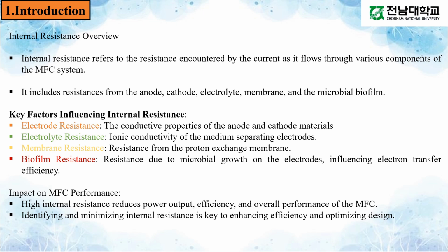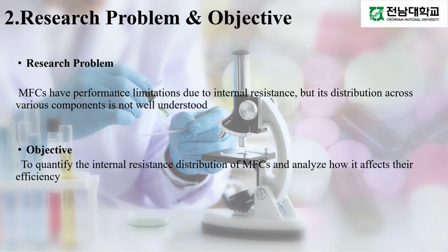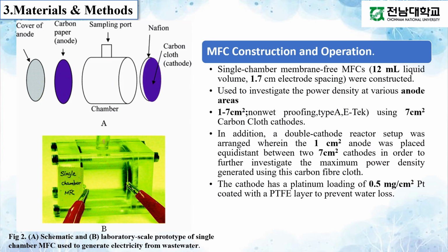The research problem of this article is that microbial fuel cells have performance limitations due to internal resistance, but its distribution across various components is not well understood. The objective of this article is to quantify the internal resistance distribution of microbial fuel cells and analyze how it affects their efficiency. Figure 2 shows the A schematic and B laboratory-scale prototype of single-chamber microbial fuel cells used to generate electricity from wastewater.